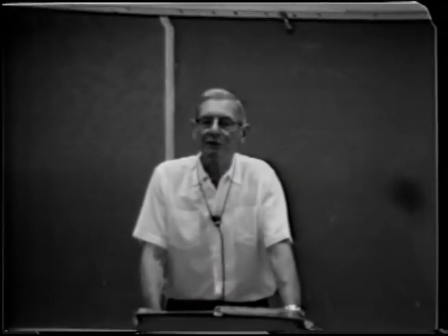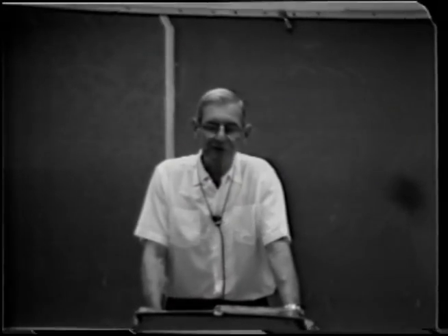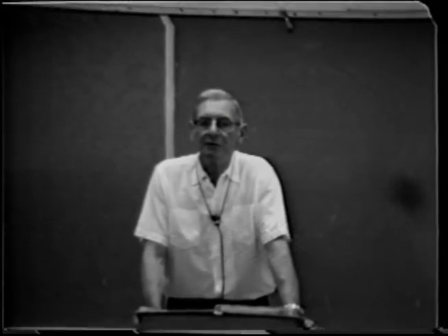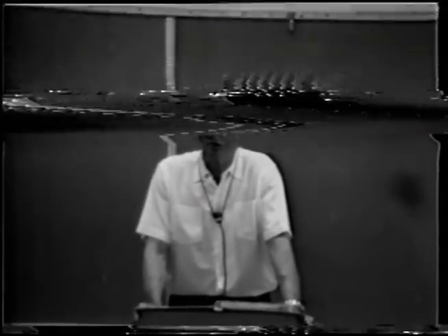If they use the plate and frame type, then you can stick to these time-temperature relationships, apply a fudge factor to give yourself some leeway of, say, 50%, and you can be sure that you won't have any trouble as far as sterilizing the wine is concerned.